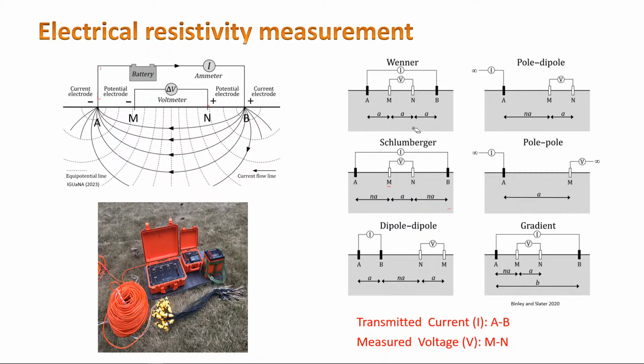But with each instrument you get, it will have a manual and it will show you what this instrument can do. Because you lay out your electrodes and then your instrument, because you generally don't lay the full set of electrodes. Like the instrument we have, each of these lines, you can lay 12 electrodes. So the instrument we have, we can lay 48 of these.